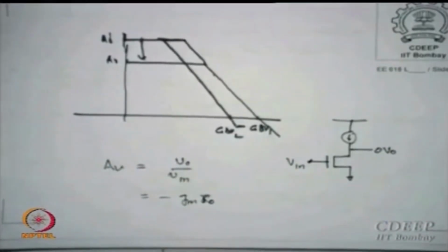So what I am going to do now is, I have a cascode which has more than one transistor sitting there in series, and therefore I will ask whether I can get GM effective and RO effective so that the gain remains GM RO.